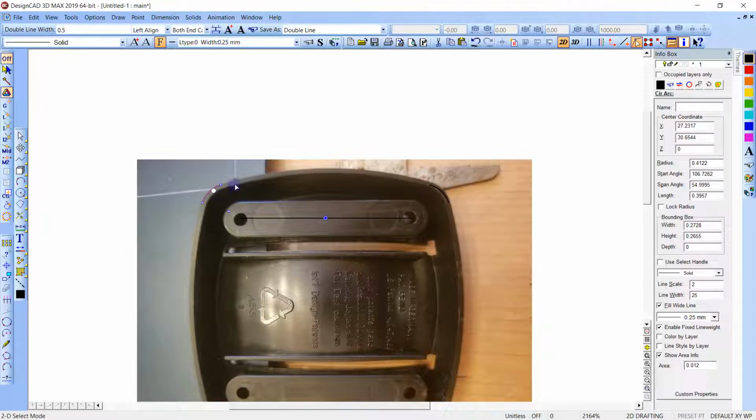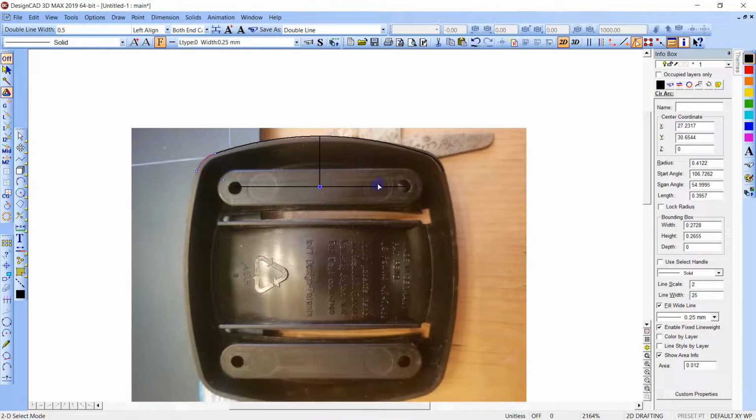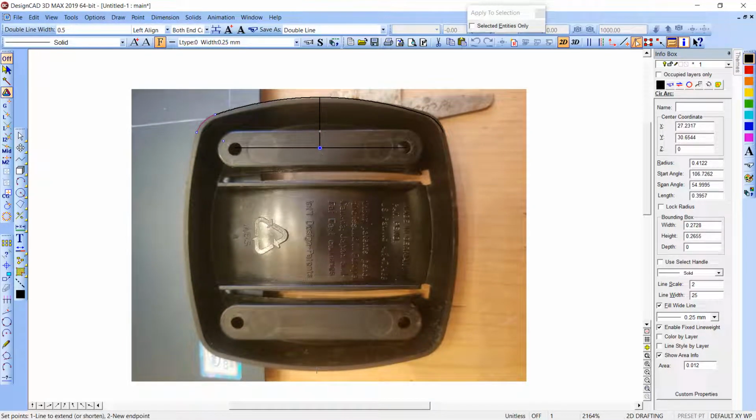Now I have a radius there and a radius there. So I can draw the same thing, 3-point radius right there. Actually, I need a little help here. So I'm going to hit H from the center. I want it to be symmetrical, which makes things a little easier down the road. Right click there, H, right click there, and then right click to the point of tangency on the other radius. Then we're just going to reflect that. So I'm going to hit shift, underline, and bring this line down to there.